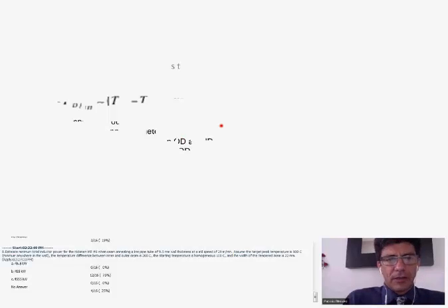So let's consider a tube of 9.5 millimeters and a mill speed of 38 meters per minute. All these are realistic numbers of a product that we make. Let's say that the distance between the exit of inductor 3 and the entry of inductor 4 is 0.8 meters. And let's assume that the temperature difference coming out of inductor 3 is 100 degrees C. So what do you think is going to be the temperature difference coming into inductor 4? I'm going to put the formula back here.